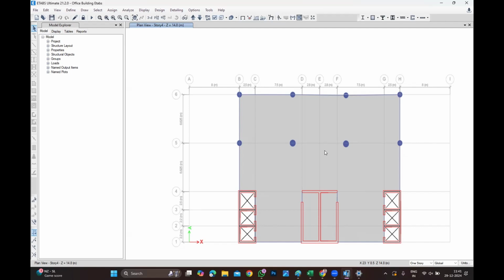We assigned a diaphragm, but then we connected only to the walls. You removed it from all of the... No, we did not do it. Okay, we did a diaphragm, multiple floors. And what it does is, based on the shape of the buildings and based on your lateral stability system, the CR, center of rigidity, is automatically going to get adjusted in the model.